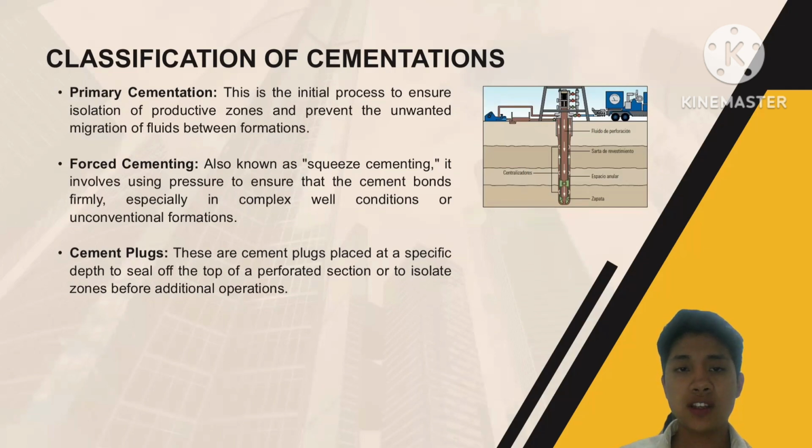The second type is forced cementing, also called squeeze cementing. In this process, pressure is applied to force the cement into specific areas to strengthen bonding, particularly in wells with challenging conditions or unconventional designs. Lastly, we have cement plugs.